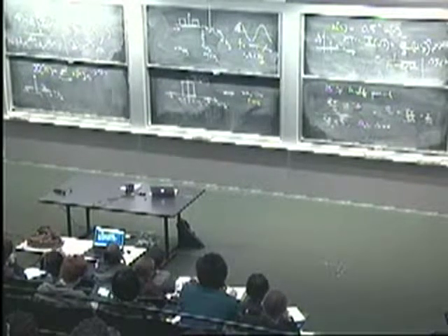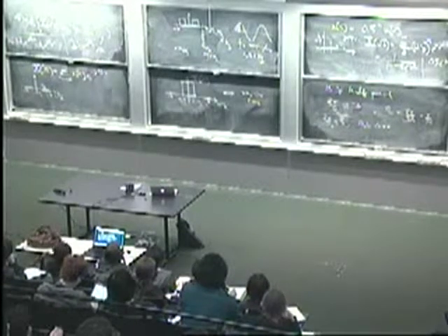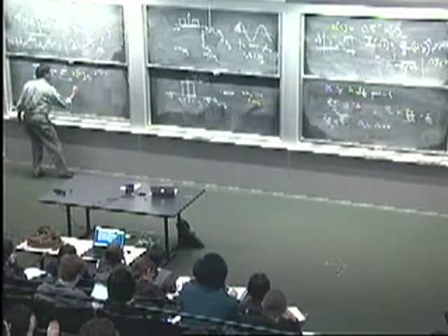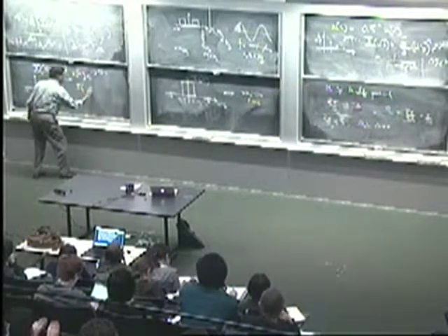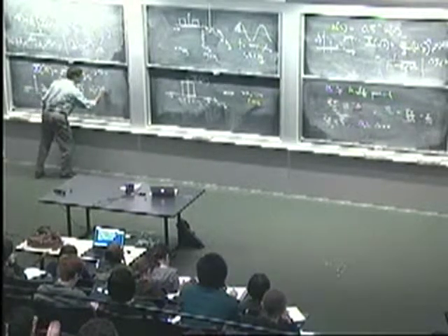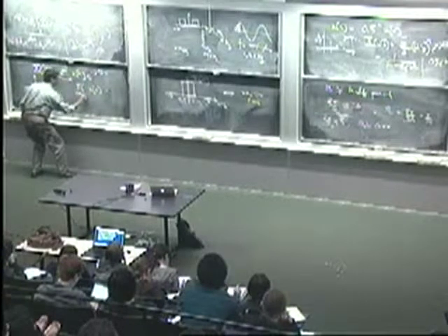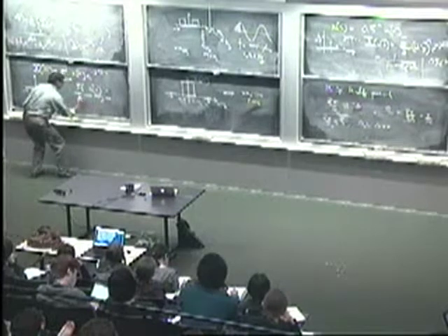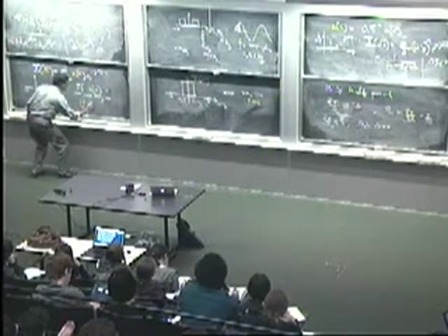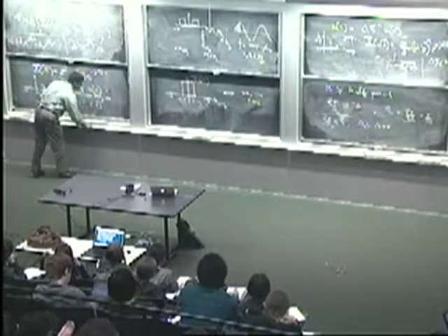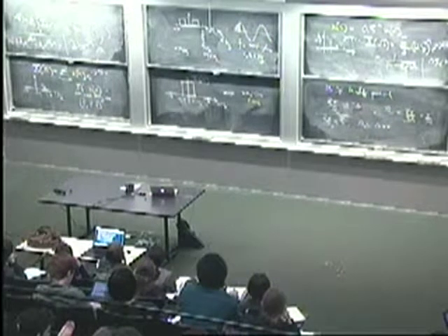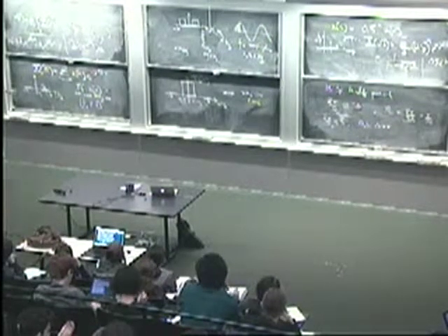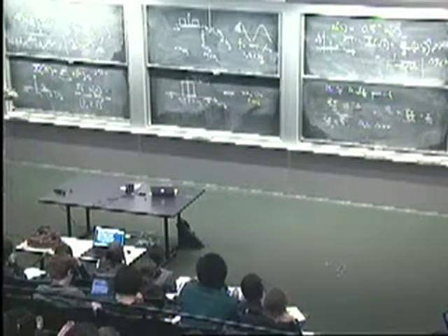Now, the interesting thing is that if your signal is 0 outside of this interval, well, that means your signal is completely specified. If x of n is known to be non-zero only on the interval, let's say 0 to p minus 1, so that's p values, then you would hope that just having p samples of the DTFT will allow you to go the other way.